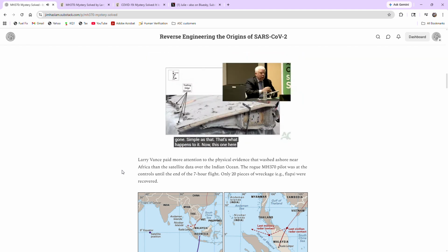Now, this one here is the back. You can concentrate here on the back edge, the trailing edge of this flaperon. And you see the damage back there. The front edge is pristine, right? It's got a nice smooth round, no damage, nothing. The back end is all eaten away. It looks like somebody got hungry and just chewed it away, right? It's all eroded, what we call erosion.